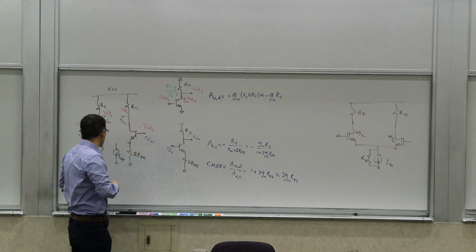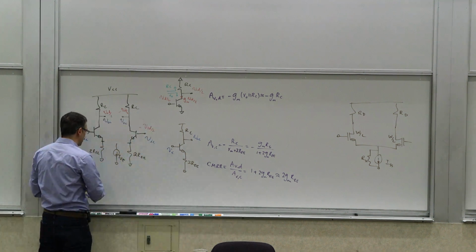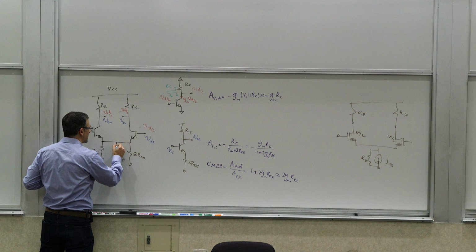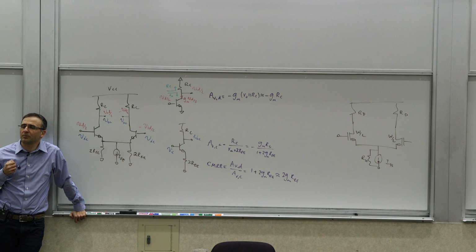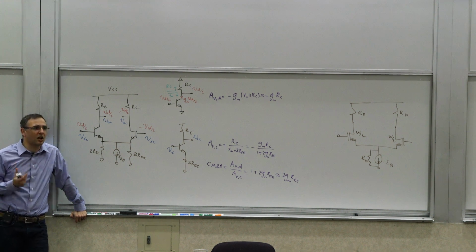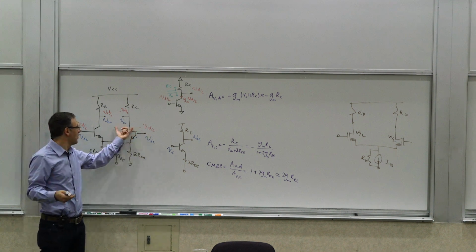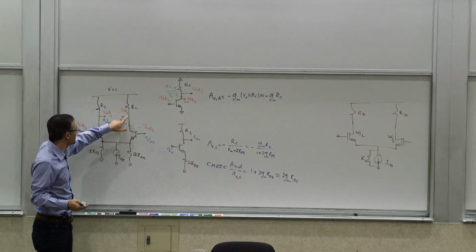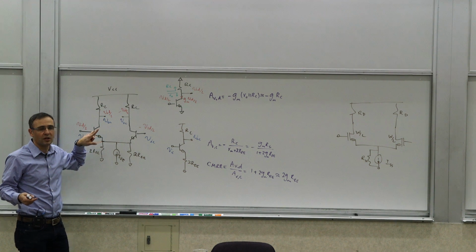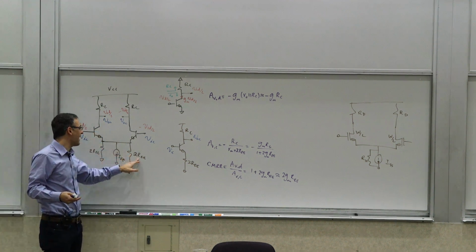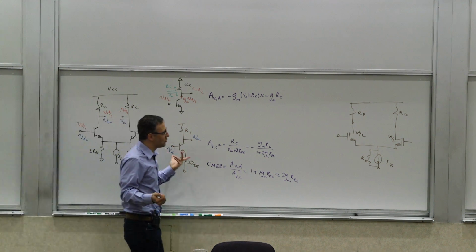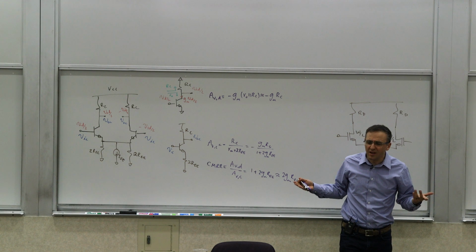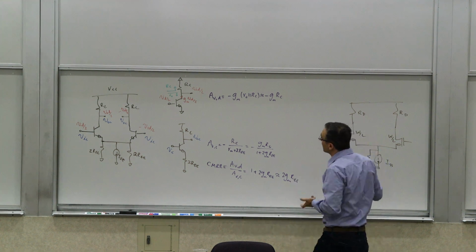So you can see the size of the output resistance of this current source is essential. And it makes sense, because this current source's purpose is to keep the total current constant, right? So if something changes in both of them, neither one of them changes its operating point or current, and therefore the output voltage doesn't change. And the less ideal a current source you have, the smaller this resistor is, the lower this effect will be. So we saw that, and that was the basis for the basic operation.